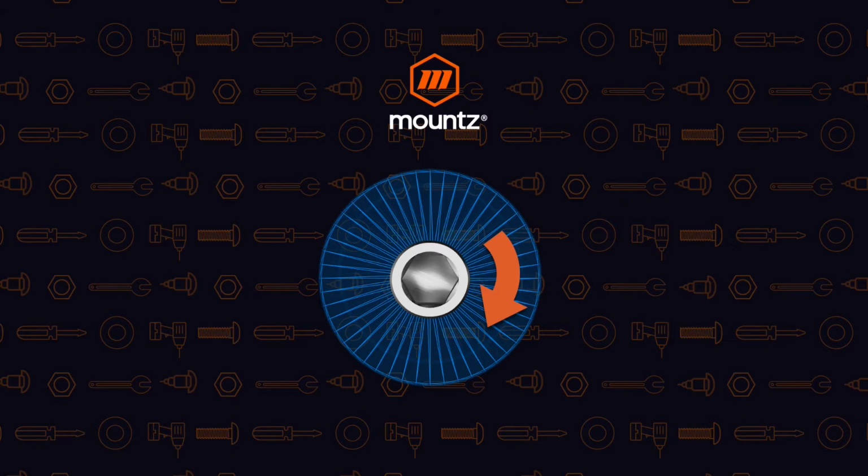But sometimes you may see an initial spike in torque and then a drop for the first few degrees of rotation, because in order for us to get the fastener moving again, we actually need to create a little bit more torque. But once it starts moving again, we have from about 3 to 5, sometimes to 10 degrees of movement to see what that initial torque value is. And then from there, again, we can develop some type of correlation to what the tool is set at, what it is performing at, and what output we are getting with the test. And that measure of uncertainty will give us the ability to do that correlation to what that value is.